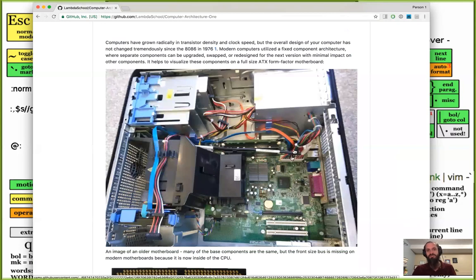And when that's finished, there's a special wire coming from the hard drive controller called an interrupt controller, or an interrupt signal pipe, I'm not sure. There's a single wire that connects through that hard drive controller, through the front side bus, all the way to the CPU. When it's done loading data, it just flips that wire and says, "Dear CPU, I got the data." And that's an interrupt. It's a physical event that changes the CPU's operation, that causes it to load instructions from another place and resume reading the data that it told the hard drive to read a while ago.